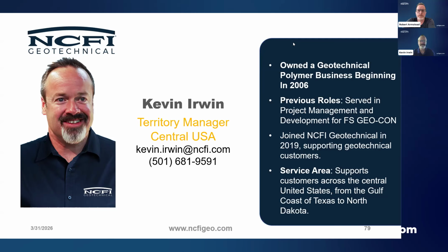But some other ways too is upfront communication. If you are walking into a situation where site conditions are unknown because you don't have a soil report, there might be concerns that there's a void or something to that effect. You need to preliminarily state, even in your contract, that this is based upon the site conditions as known. As site conditions change, this may change our overall approach and the overall costs and negate the ultimate value. But if it's able to be pre-communicated and you think there might be a potential void there, bring the appropriate material along, and communicate with the homeowner or the engineer ahead of time.